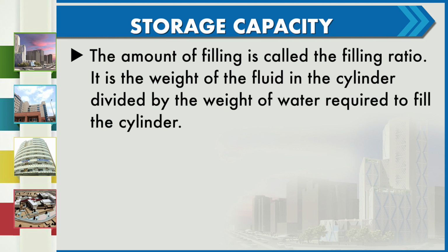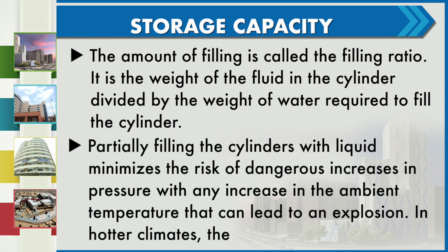It is the weight of the fluid in the cylinder divided by the weight of water required to fill the cylinder. Partially filling the cylinders with liquid minimizes the risk of dangers. In hotter climates, the filling ratio is 0.67. We now come to medical gas supply system.